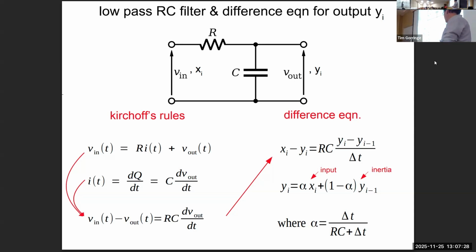So it's an ordinary differential equation, first order with respect to time. It incorporates the input voltage that we're going to specify, and then it tells us the output voltage in terms of the circuit arrangement, the circuit components, the resistor and the capacitor. Let's turn this into a difference equation now. So we've written down an analog differential equation based on current and voltage rules. Now we're going to turn it into a difference equation that we can use in an algorithm in our digital signal processing.